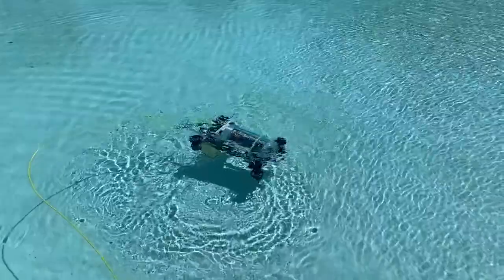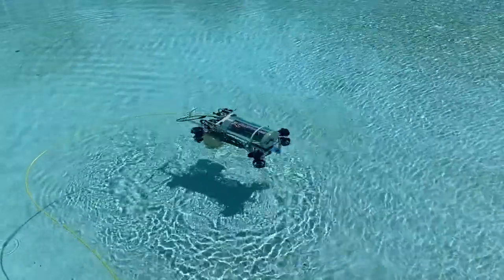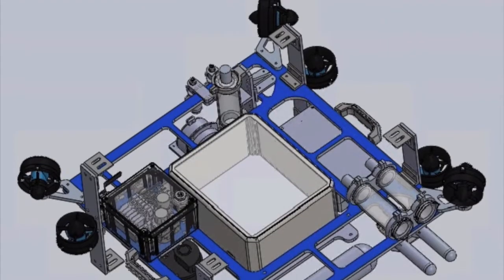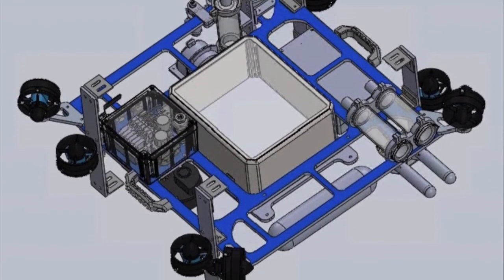We were able to do some additional mechanical testing in the large sink in our lab. There, we again verified that our robot frame and thruster placement could achieve 6 degrees of freedom. We also found that we were able to use significantly less power compared to last year for a roll, since our thrusters were more widely spaced apart, so that increased their torque. One thing we did realize in the sink was that 8 of the thrusters would have to be protected so they didn't get banged up during our rotations.